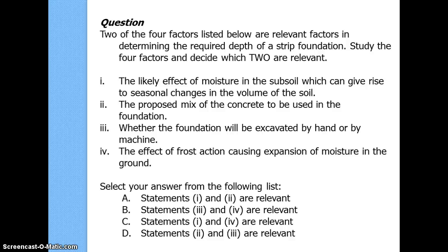That is a relevant factor. Number 2, the proposed mix of concrete to be used in the foundation. That's not a relevant factor. Number 3, whether the foundation will be excavated by hand or by machine is not relevant. And finally, the effect of frost action. That is a relevant factor. So 1 and 4 are the relevant factors, so the correct answer to this question then is C.